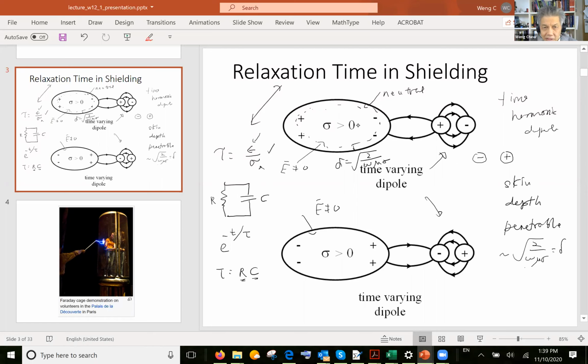So there's a time constant involved in the relaxation of the charges as they move back and forth between the two ends, very similar to how current would flow. Say you have current flowing, and then it will have to be discharged on the next cycle. As the charge is charging the capacitor and getting discharged from the capacitor, the charge and discharge time follows this RC time constant. Okay, is this clear? This is just an approximate concept.